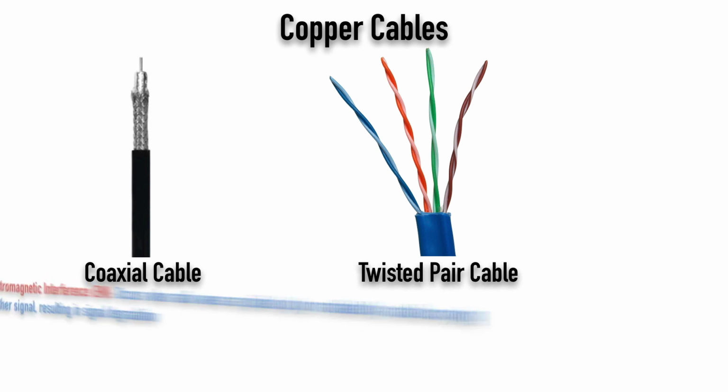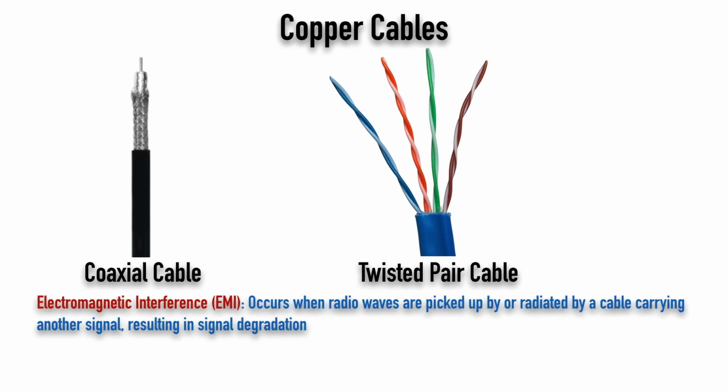You see, one thing we're trying to prevent with either of these types of cable is EMI, electromagnetic interference. We don't want radio waves to come into one of these wires and corrupt the signal being transmitted over the wires. Also, we don't want those wires to become antennas and start transmitting their own signals and interfering with other things. So with the coaxial cable, we have that sort of a mesh of wire that's surrounding an insulator, that's surrounding an inner conductor. So that outer mesh of wire, that's providing the insulation from EMI.